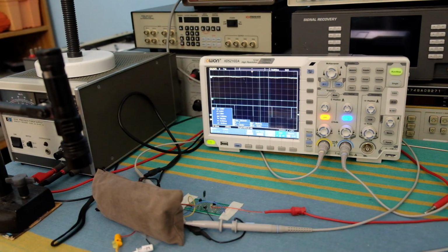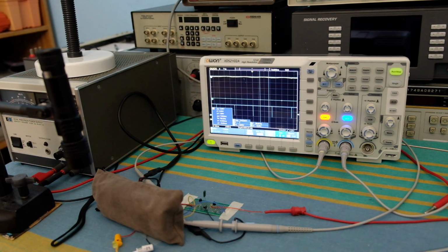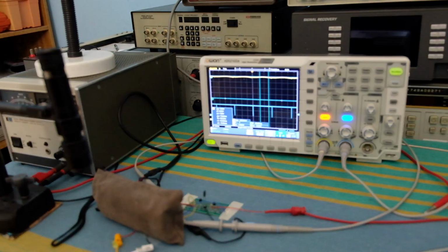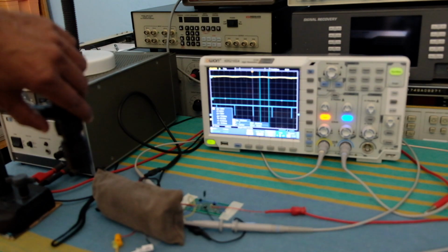So far we looked at different LEDs and different integration caps. We looked at the 3 nanofarad, 1 nanofarad and a 330 picofarad cap, and several LEDs. It's more interesting when you have a large amount of current. You can see it saturating, and to get rid of the saturation, you increase the capacitance value as I did. But here's another thing I want to show you, which is modulation.